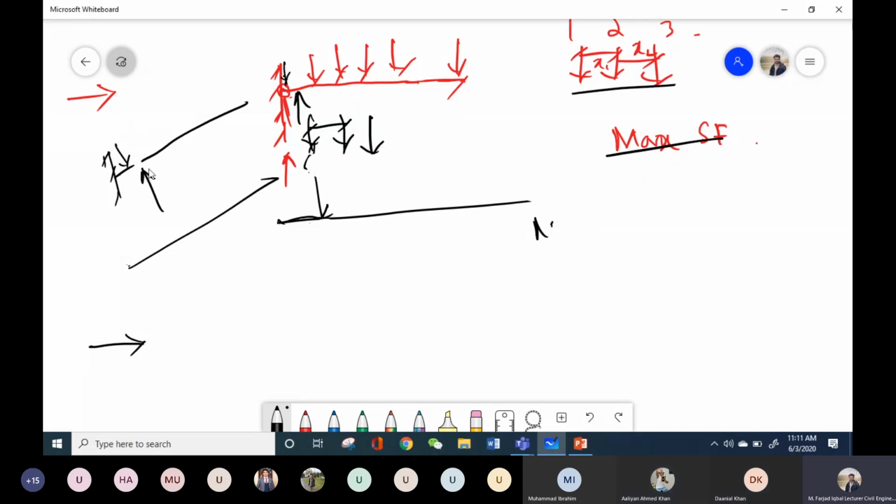So this right part will move up as a whole, and this is my shape of ILD for this shear force. Thanks for pointing out. So this is my shape of ILD for shear force, and I will place my moving load at, let's suppose, these points, and I will get the maximum value of shear force for this beam.